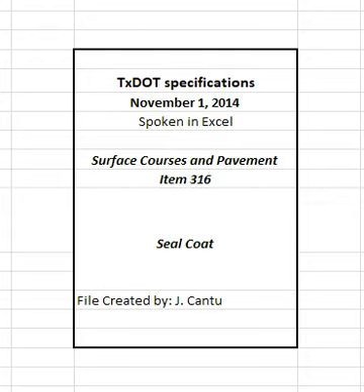Manufacturer and grade of asphalt cement. Manufacturer and grade of crumb rubber. Manufacturer, type, and percentage of extender oil, if used. Test report on crumb rubber gradation in accordance with Tex-200-F, Part I. Design percentage of crumb rubber versus asphalt content.